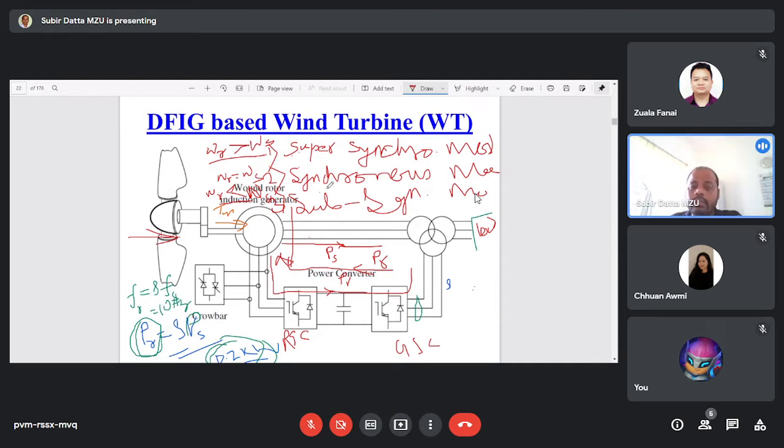So in that case, you just see, in order to get the synchronous mode, we know that for synchronous machine operations, we have to use the excitation system. Okay, without a separate excitation system, we will not be able to interlock the rotor magnetic field and the stator magnetic field. So we have to use an external circuit. Using that external circuit, we can excite the electrical machines, and using that excitation system or excitation circuit, we can operate the system at a constant frequency, or you can say at a constant speed.